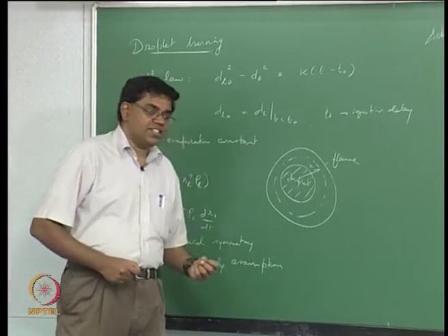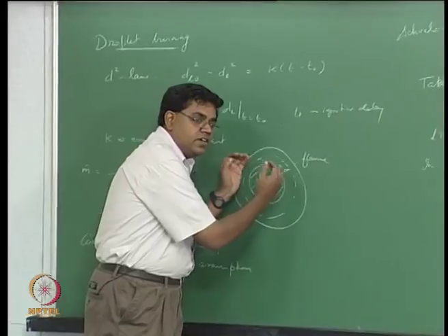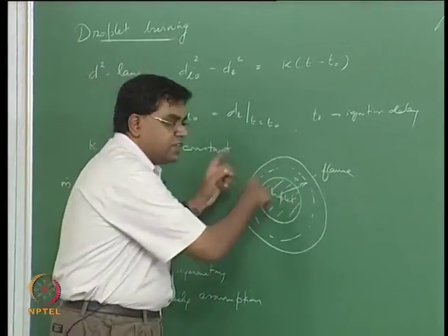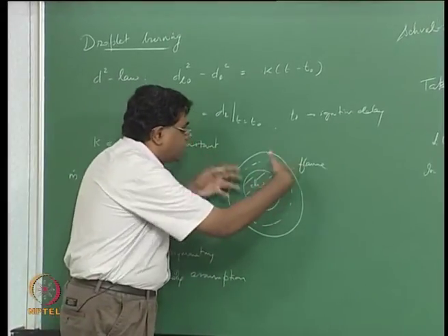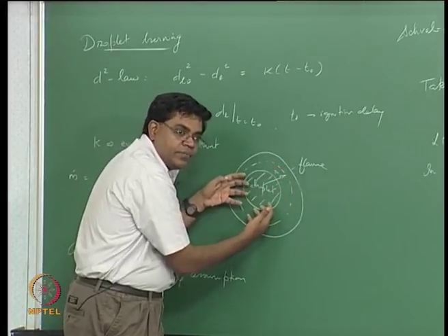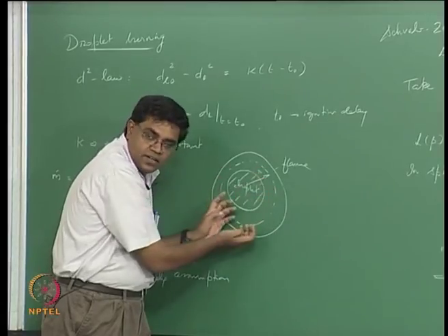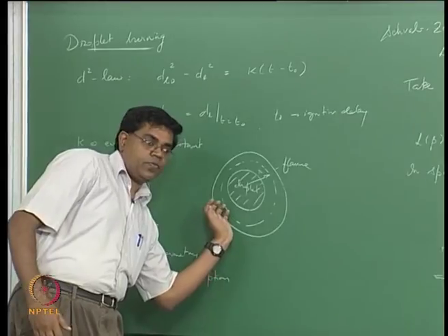As opposed to that, if you now look at aluminum, since the aluminum oxide is immiscible in aluminum because of interface tension forces similar to surface tension effects, all the aluminum oxide that is coming in cannot really stick at different points, so it tends to accumulate to one side, and forms what's called an oxide lobe on one side.